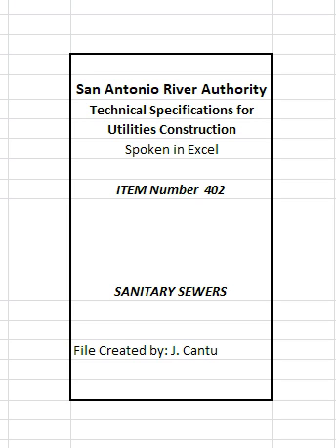D. All interceptors shall have the size of the interceptor, in gallon per minute or gallon capacity, permanently affixed to the device. E. All concrete utilized in the construction of interceptor shall have a minimum strength of 3,000 psi. F. An effluent sampling well on all interceptors shall be required.